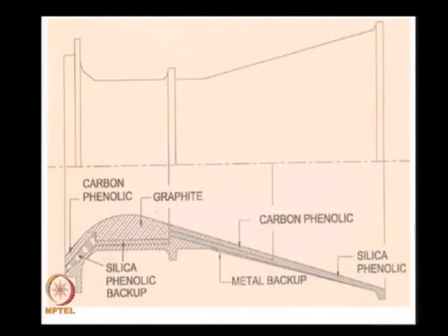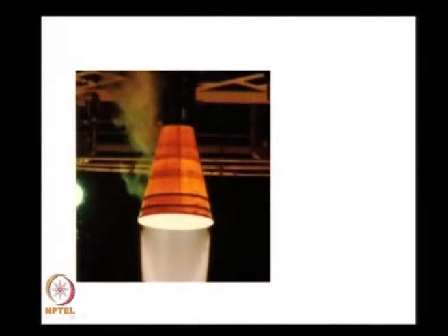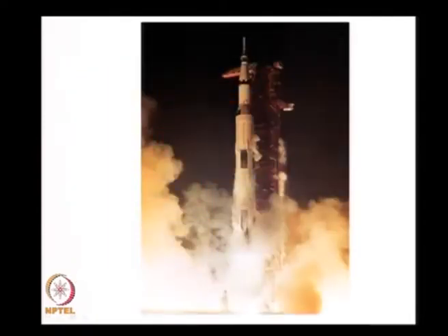I will get back to this slide a little later in the course, but this is how a practical nozzle looks like. This is the outer surface, this is the inner wall of this. I repeat this, a nozzle firing for a certain amount of time. This is a conical nozzle. You see that the nozzle runs red hot and you have the flow taking place, and this is where we said I have the waves and all that, and we talked in terms of shock diamonds. Well, with that we close the portion on nozzles, but it will be incomplete without doing one or two problems.